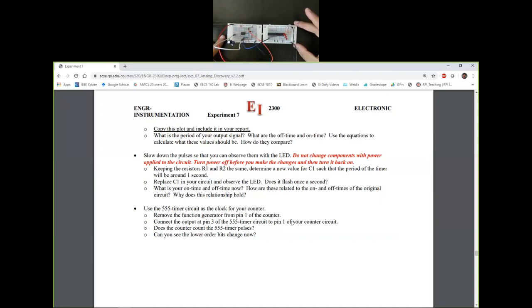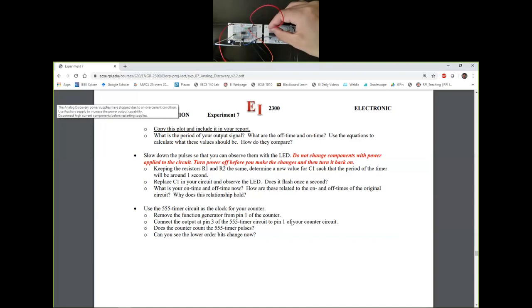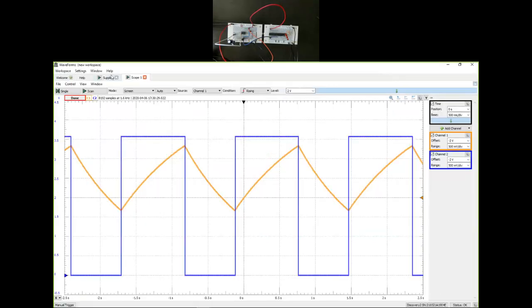So it is going to pin number 1 of an inverter. It gets inverted and then that feeds into the clock input of the counter, which is the middle chip over here. But this guy is not going to go until I give it power and ground. So I'm going to take a copy of the power from the board on the left, and also I'm going to connect ground. So let's see, ground needs to be connected as well. So a copy of ground is given, a copy of this guy is given as well. Hold on, what? Yeah, that was a bad idea. Oh yeah, my supplies are off.